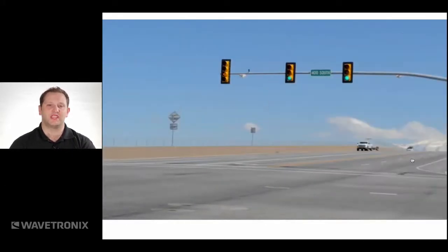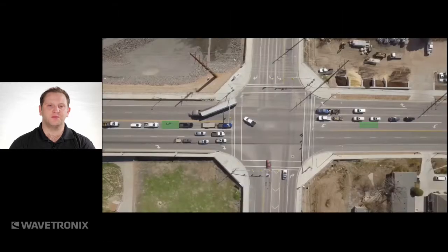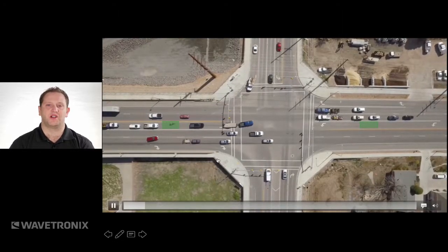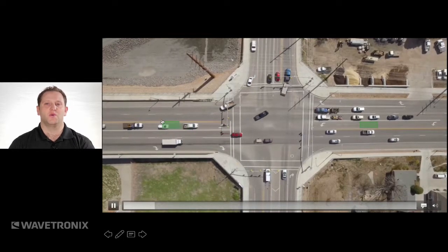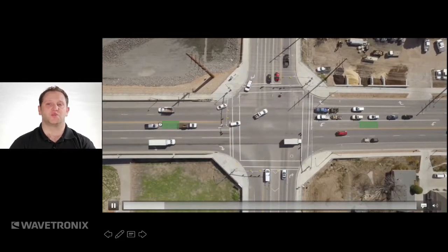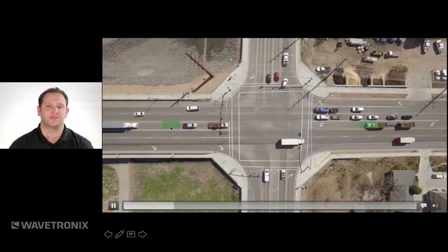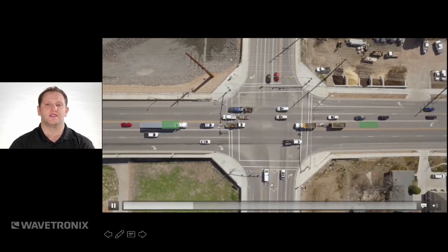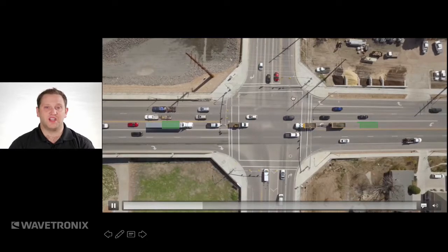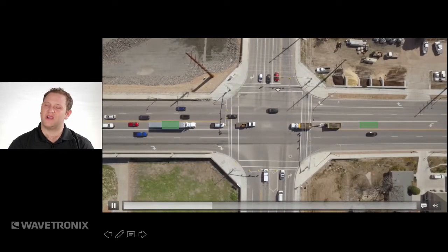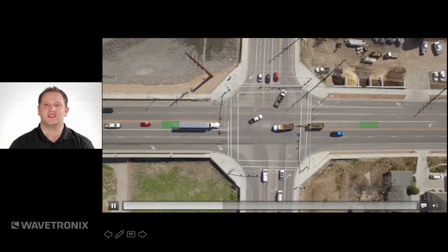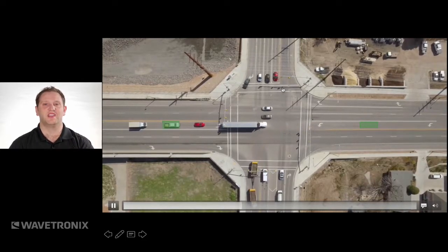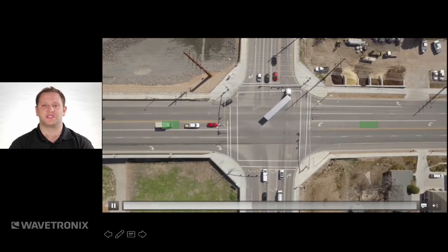Let's say you wanted to get a green arrow. So let me show you a little bit here. When you're doing detection zones for a flashing yellow arrow, you want to place the zone where the third car back in the queue would sit. So for example, it's at where the green square is at this intersection. Although at the top here you can see that it's a double left. I would be cautious about using a flashing yellow arrow on a double left. You wouldn't want to do that. You'd really only want to do it on single left-hand turns.